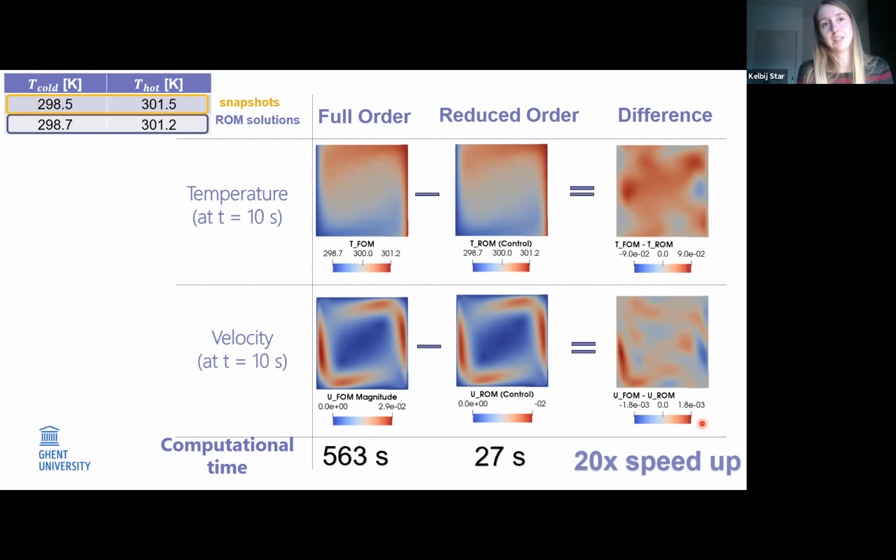So in that case, it's better to develop reduced order models, for example, for the part that's in the laminar regime, and then use the final solution of your first reduced order model as the initial condition for your second reduced order model for the transition regime, and so you can work through it.